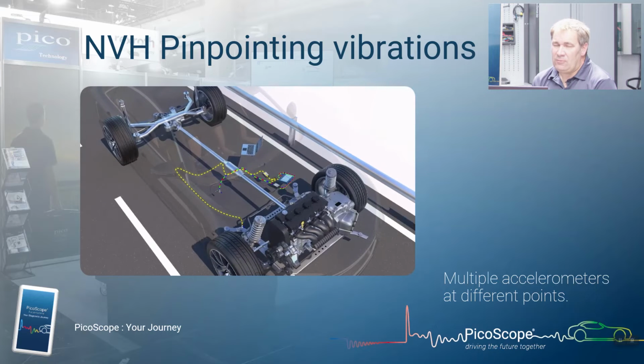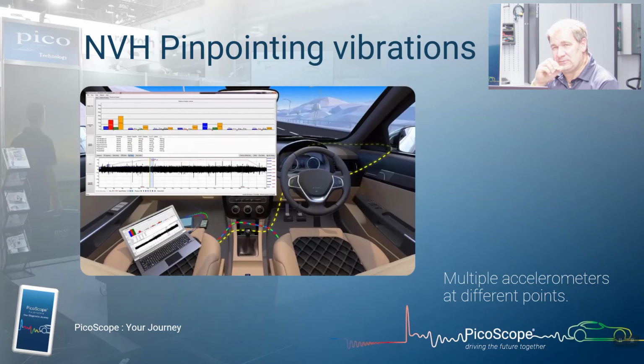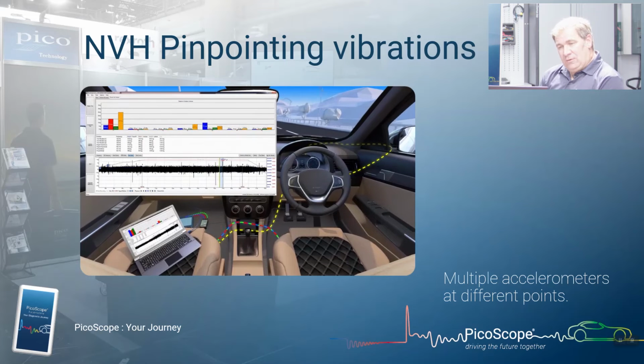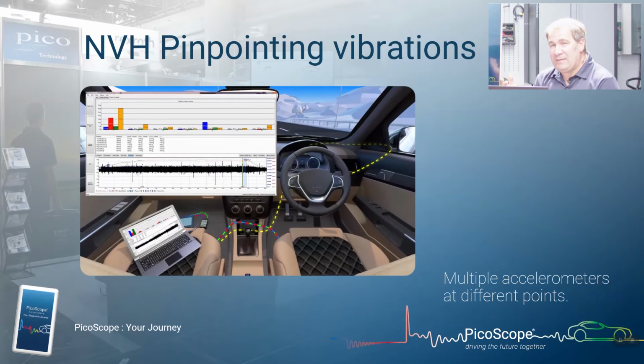So same road test. Really important thing around road tests, different roads have different feelings. So if you're doing multiple road tests, it's really quite useful to keep all the variables to a minimum. So going on the same route each time will really help you when you're capturing data. And what I didn't mention was, on our second one, because we're generally limited to 4 channels, and I don't feel that's a problem, because we are looking at the up and down movement, we've just connected into the up and down movement on this accelerometer for the second measurement in the engine bay.